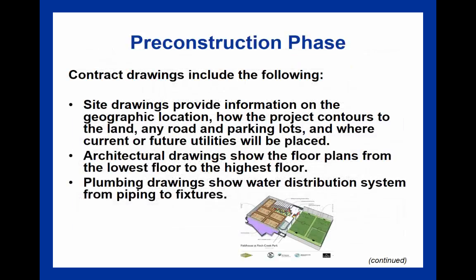Now, once the request for bidding or request for qualifications go out, and the bids have been reviewed, and there's an appropriate contractor that has been chosen, and of course the contract's been signed, then we would move on to the pre-construction phase. And in the pre-construction phase, that's going to be where a lot of documentation comes into play. And remember, once you select the appropriate contractor, we also need to understand whether or not there's going to be guarantees that the work will be completed.